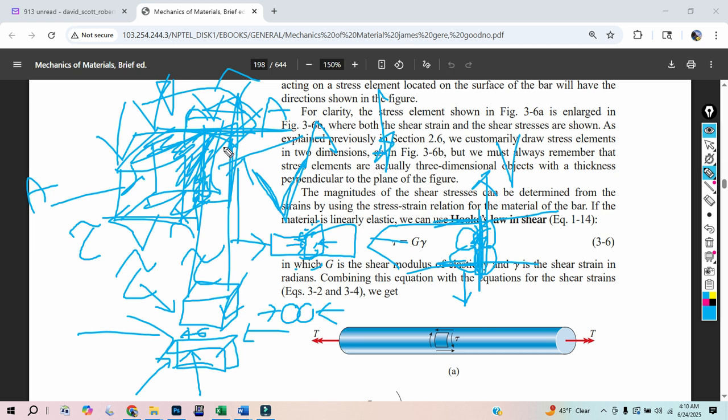You know what I mean? So there is that relationship that if I have twice as much material, same force, the PSI is half. And if it takes this big number to actually get that square bolt to shear, and then I just doubled the size of the bolt, well, I need to get that PSI with my normal force to that number, twice as big, so I need to put 2 times the force into it. Hell yeah.